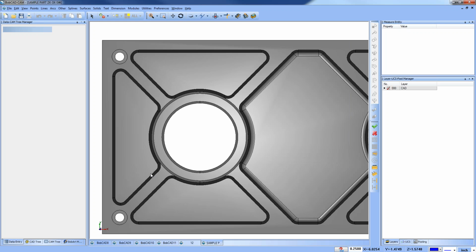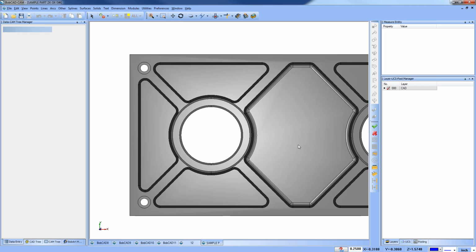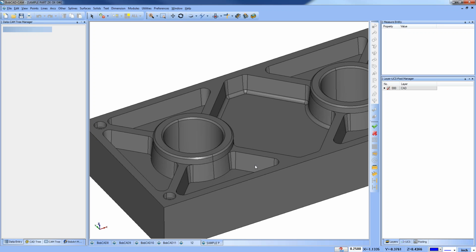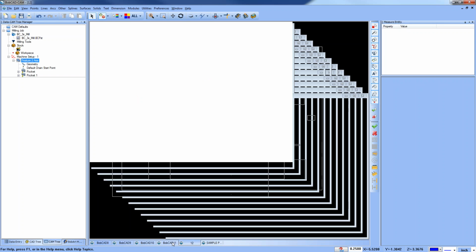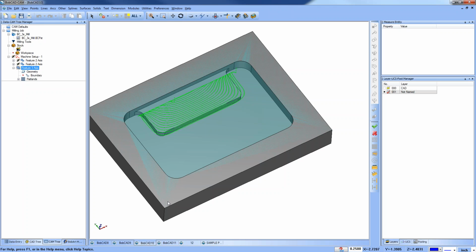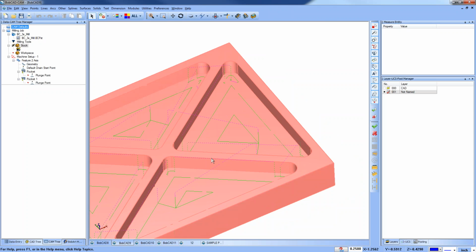And if you're dealing with tapered walled pockets like this, it's really going to come down to 2 different scenarios. Either you're going to load in some tapered tooling, or you're going to use a Z-level finish type routine. And I think a lot of people will agree that the tapered tooling is a good way to go.